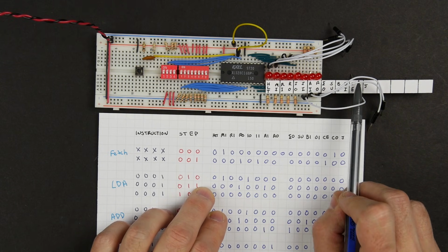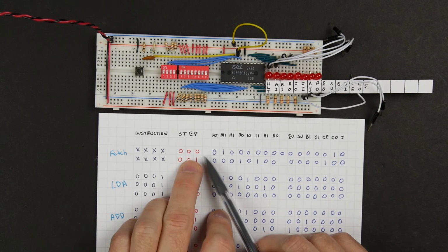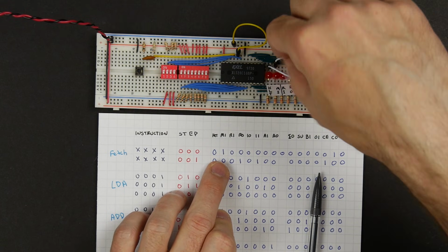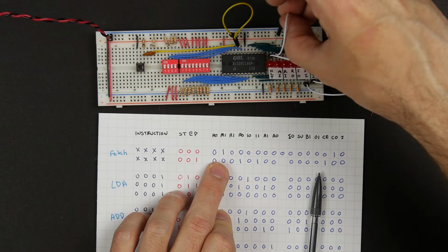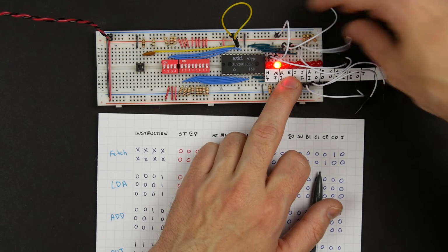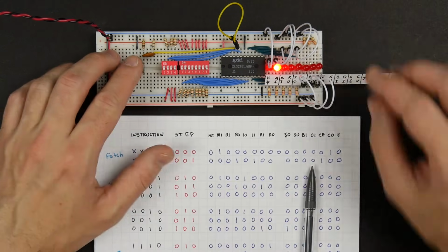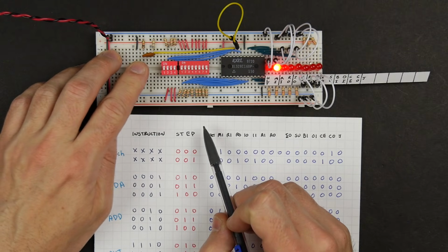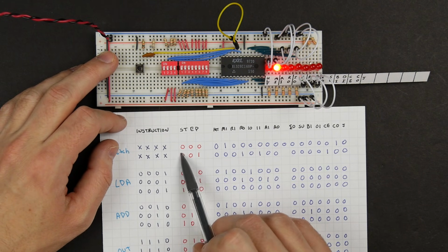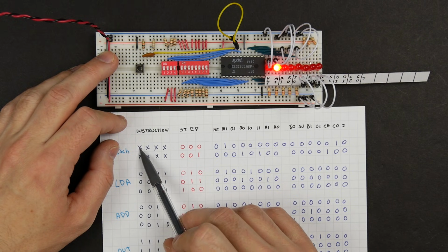So counter out is over here, that's on the other EEPROM. So for this EEPROM, it's step 0. Really all we need to program is memory in. We want to set that high. So let me set that high. There's memory in. And then the rest of the bits will set low. So I'll just tie them all to ground. And so I'll program this at address 0 by pushing that button. And so that sets it for step 0 for instruction 0, but we want it for any instruction.